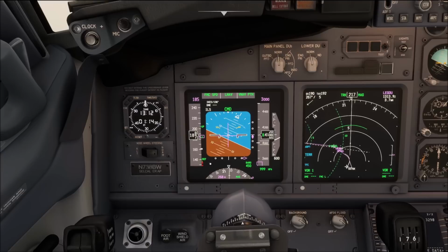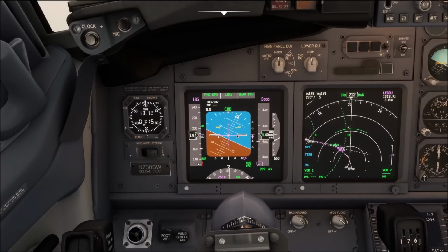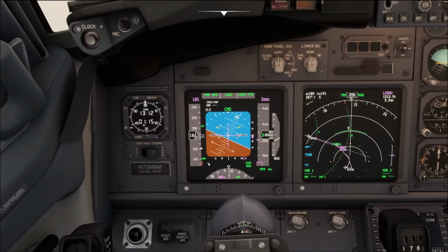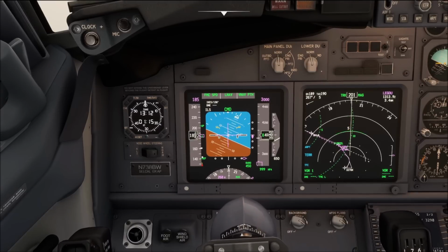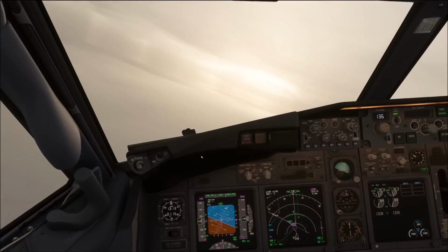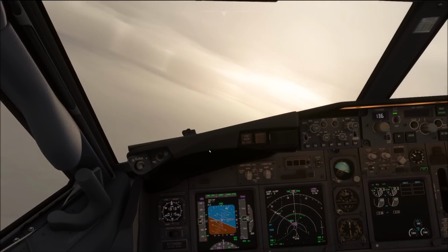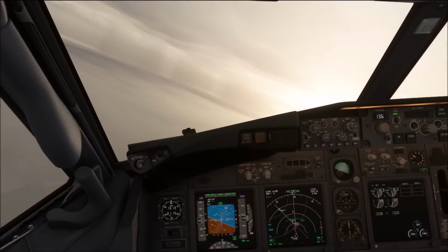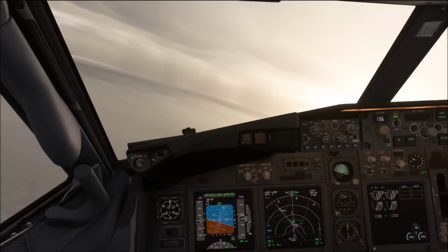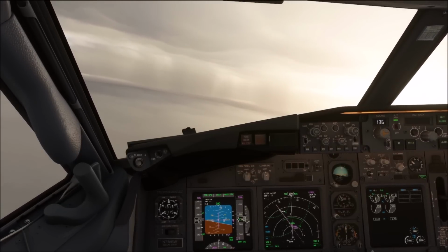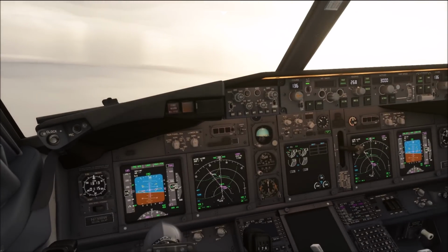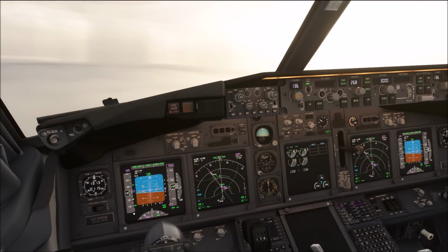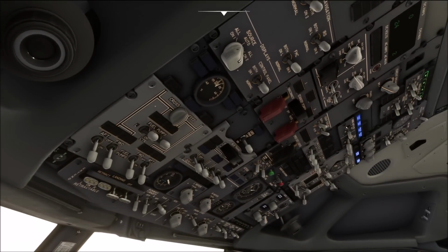So do anticipate that on the approach, and do anticipate that you will be closer to the stall speed, or rather closer to the indicated stall speed. This is independent of the length of your actual flight, so you can expect that even if you do a 4-hour flight down to somewhere where it is very warm, 30 degrees or so, the airplane is still going to give you the increased stall speed indication once wing anti-ice has been used.